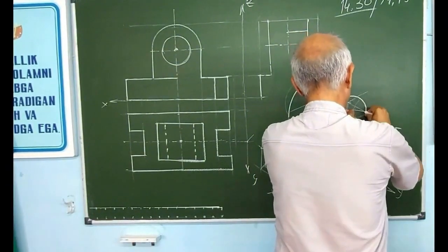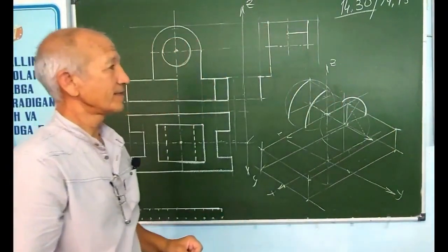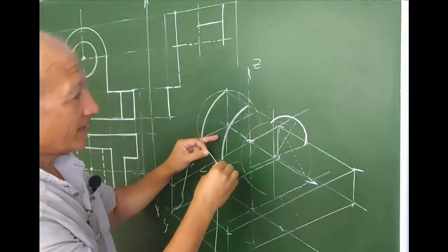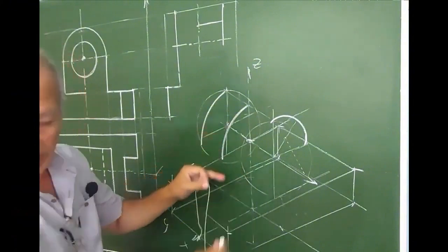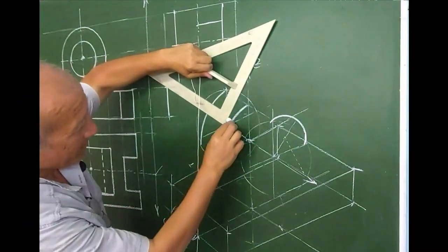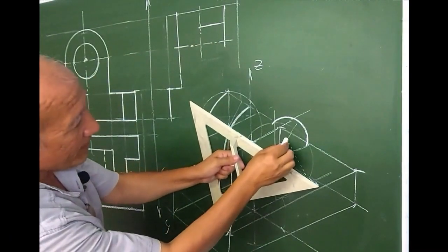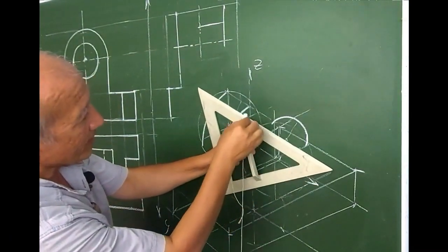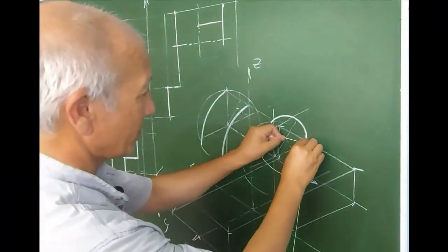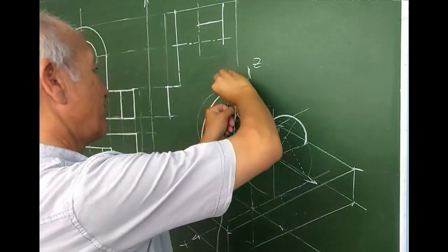Like this, you would draw an arc like this. Do you remember? Now you need to draw exactly the same thing here as well, but it's not necessary to draw it again, that's what I mean. And so you would draw this as a perpendicular here, and here is the point you found earlier. You bring that point over to this one, just like this. Here you go. You bring it over, and with this radius you set it exactly where you measured the arc, and then you bring it over like this.